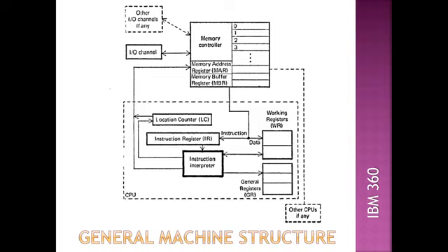Yes. The next thing is called the instruction interpreter. What the instruction interpreter does is it just decodes the instruction. It is going to see whether it is an add instruction, a multiply instruction, a subtract instruction, whatever instruction it is. So you only have add and subtract instructions here. There is no multiply instruction. Just saying, for example, it just tries to decode and understand, right?